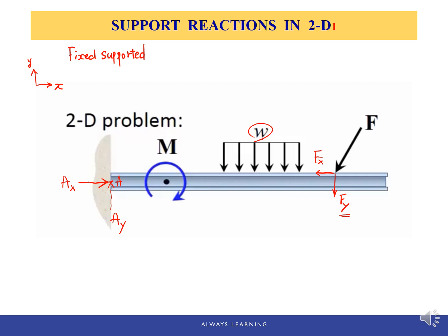And finally, this force F, especially the Fy component, will create a clockwise rotation moment about point A, and also this couple moment causes the member to rotate clockwise. So the wall also must exert a support moment that is counterclockwise in order to prevent this rotational motion.